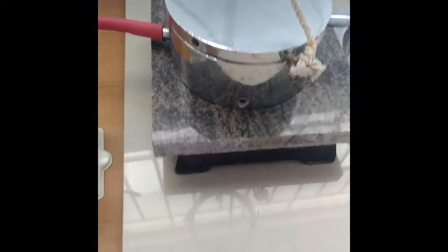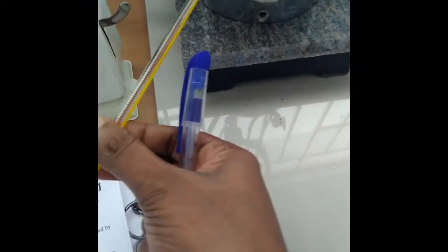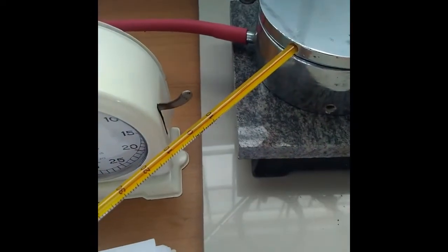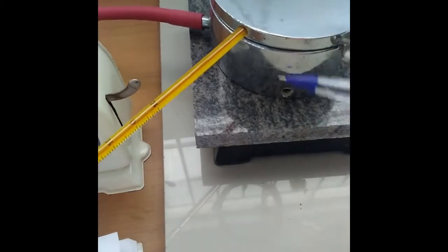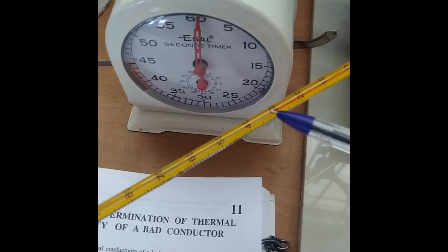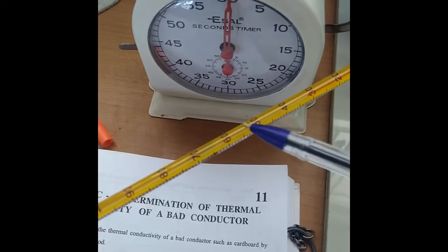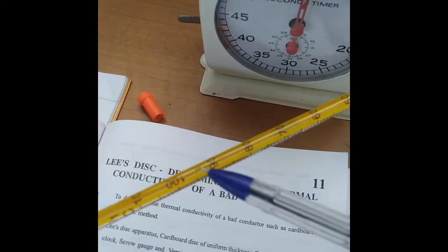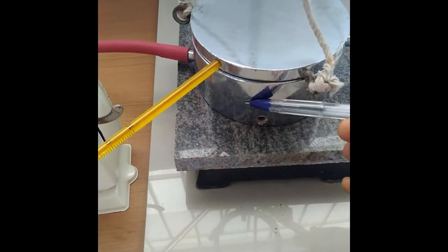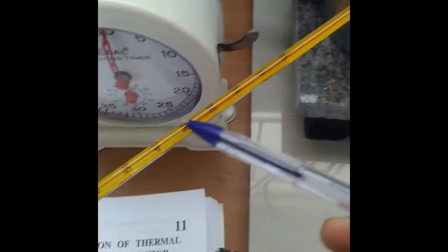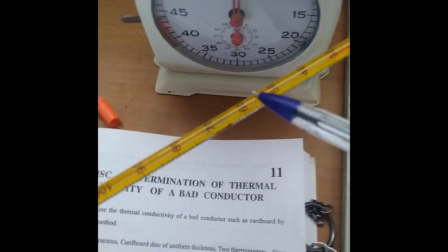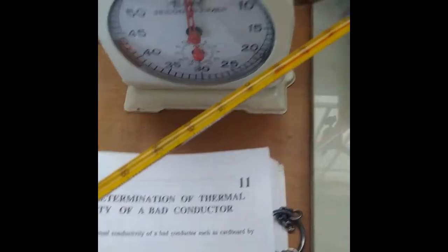Now if you put a thermometer into the Lee's disc, you can observe the rise in temperature in the Lee's disc. Why does the temperature rise in the Lee's disc? Because now the Lee's disc is in direct contact with the steam chamber. Now if you check your thermometer, it shows an increase in temperature, and again the thermometer will go to a maximum of 97 degrees Celsius, which is the steady state temperature of the steam chamber, right? So after the thermometer shows a temperature which is almost some 10 degrees greater than the steady state temperature of the Lee's disc.